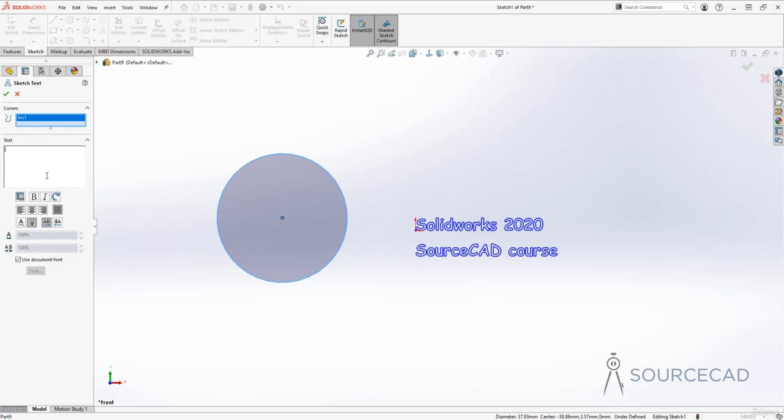Let's now type text here. So SolidWorks Professional 2020. All right, and yeah, that's our text. I'll just add single line of text here, and as you can see, this will be distributed completely along this path. Now why is this happening? Well, that's because of one of the formatting options that we have here, and that's this last one. This is full justification. So I'll just justify it towards left, and that's what we have.